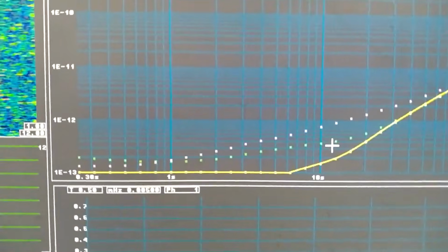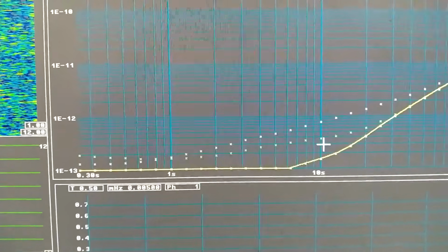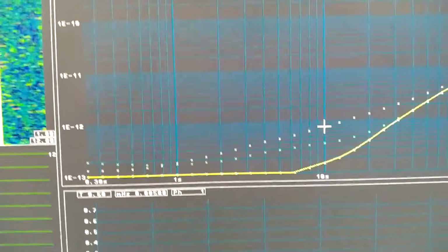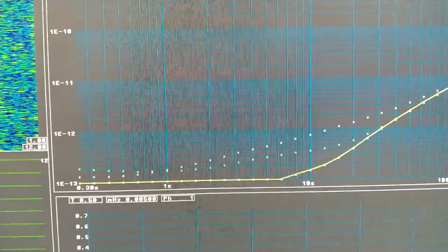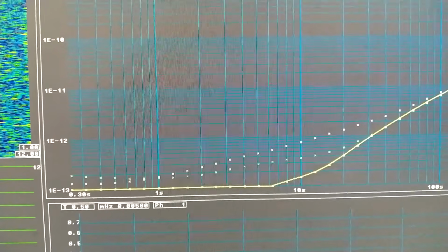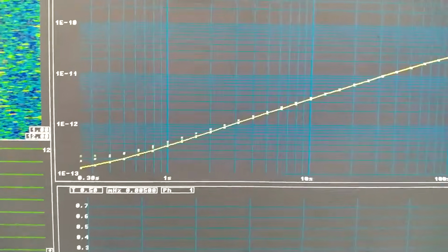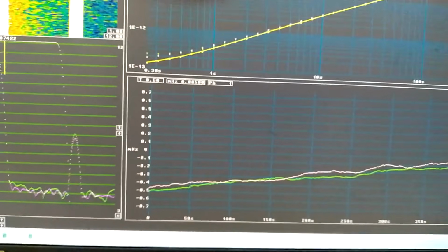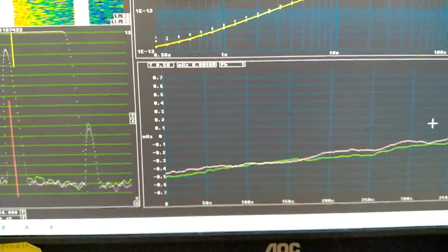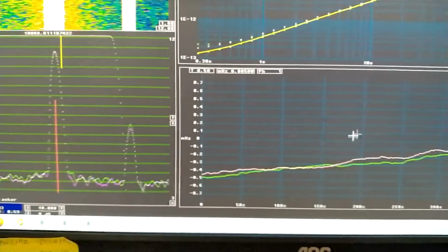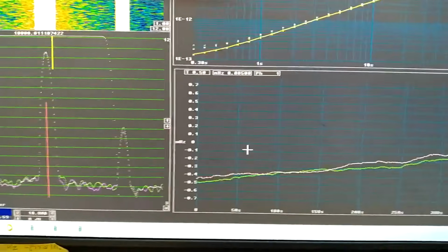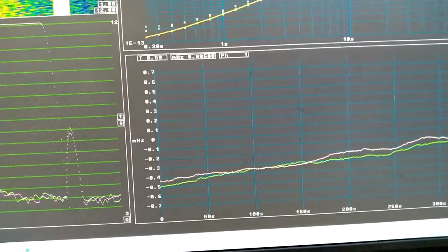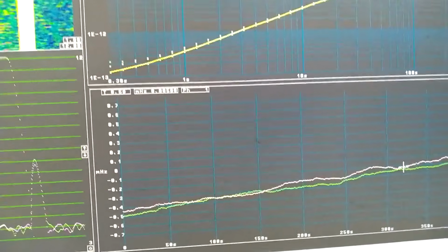But you can see here, in 10 seconds, there is a significantly more noisy signal from channel 2. And this is the Hadamard graph. If I look at the Allan, there is not any difference, because the slope here, the steady increase in the frequency, is 0.1 millihertz per division. So it is small changes, but significant.